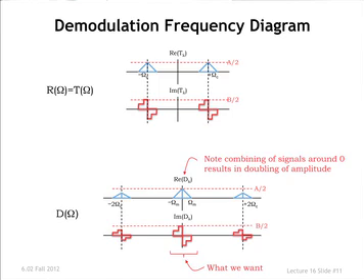So omega C would be a pretty safe choice, right? Omega C would be one that passed everything here and would basically extract any signal that satisfied that initial constraint that we mentioned. So if your baseband signal originally extended from minus omega C to plus omega C, then a low-pass filter that extracted that would do fine without pulling in any of the replication here. So omega C is certainly fine.